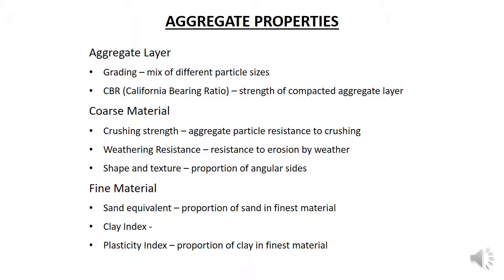Important properties of the whole aggregate mix are its grading, which is the mix of the different particle sizes, and the strength of the compacted aggregate layer, which is measured by the California bearing ratio, or CBR.